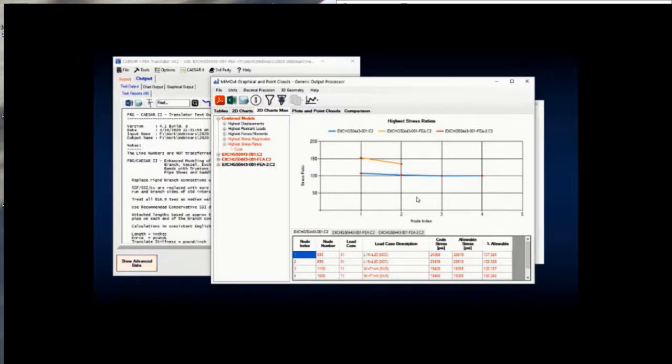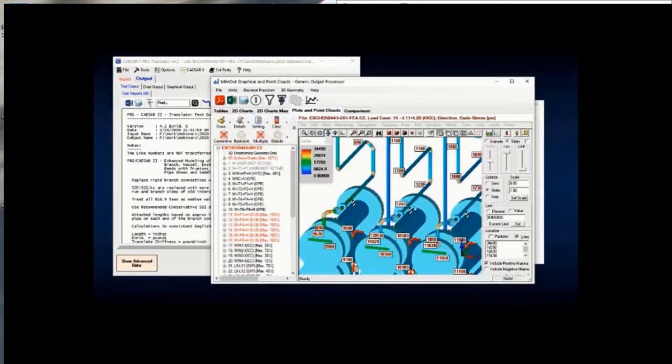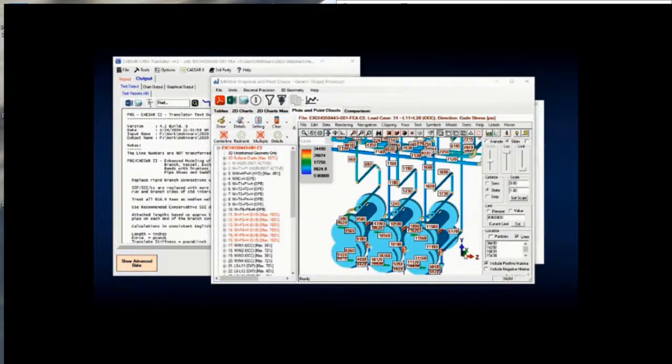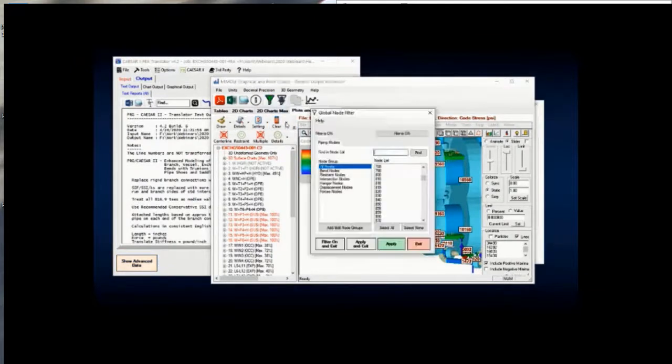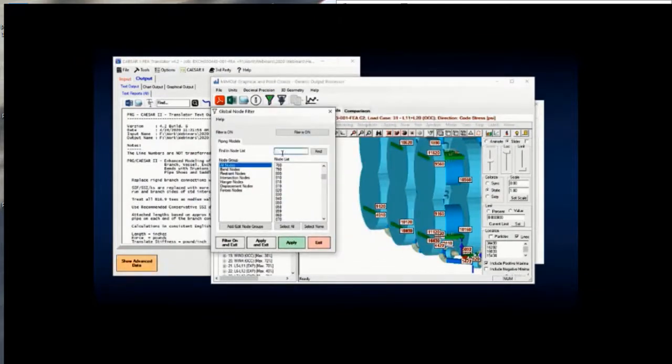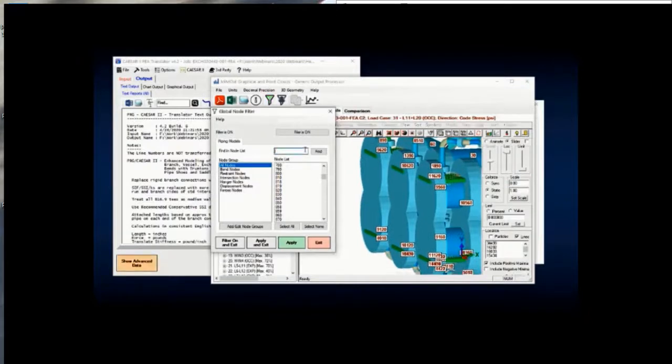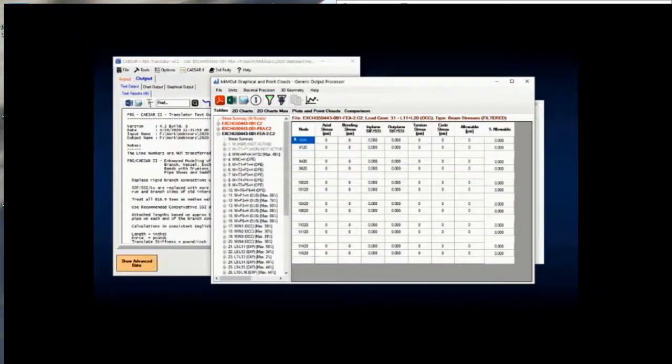Now that we have solved the overstress, we need to make sure that the loads on the heat exchangers, which are these right here, are not overstressed or overloaded based on allowable loads given from the vessel engineer, who ran Nozzle Pro and gave us the allowable loads. So now I'm going to go to filter and find 9620. These are my restraint nodes for the heat exchanger nozzles.